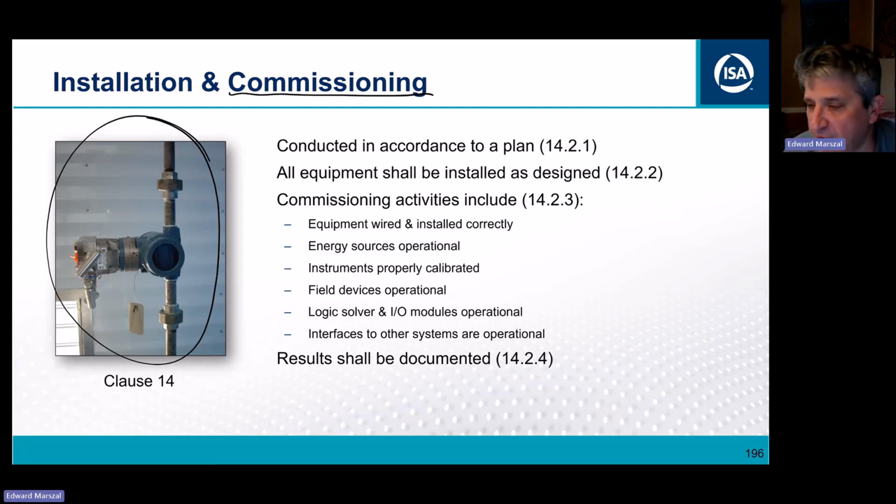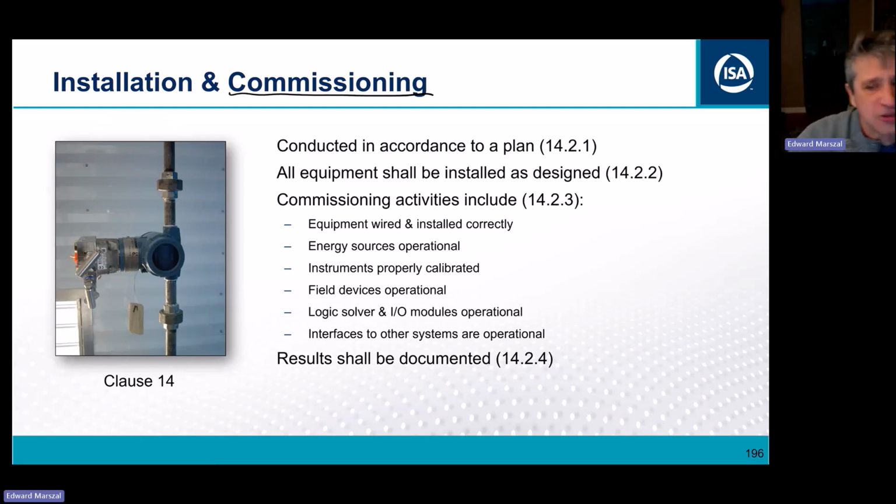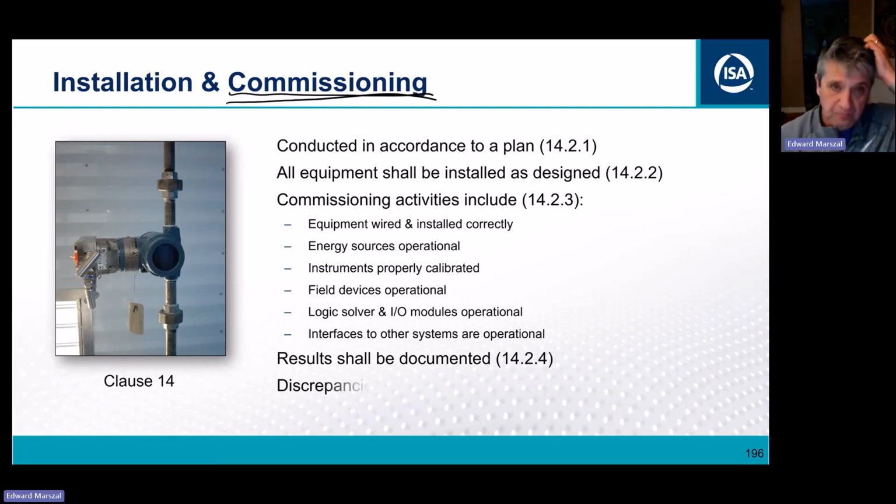You don't pipe the process through the electronics. So that didn't show up in the PFD calculation. That showed up in the commissioning, where we are back checking other people's work. And there's going to be a strong stress that says human failures need to be detected by other administrative controls, other people checking the work. That's all going to be clause 5, and I'll get back into clause 5 in a second.